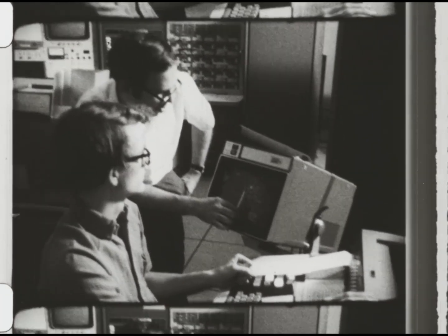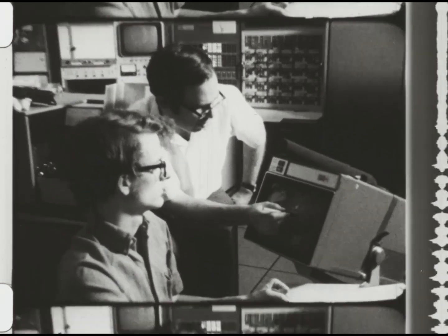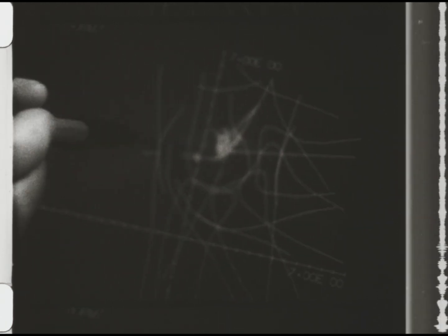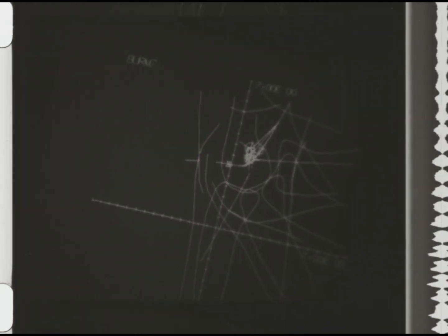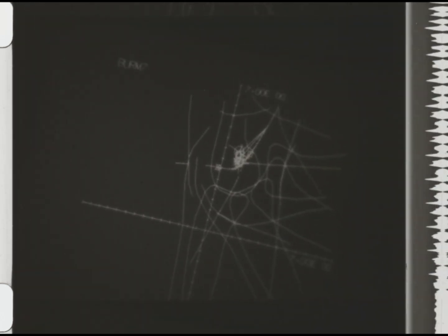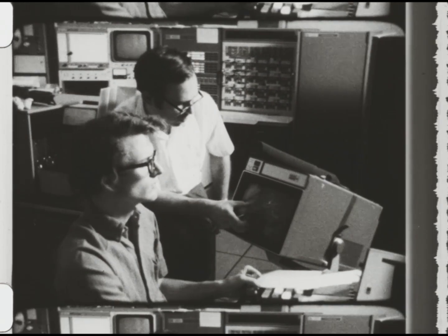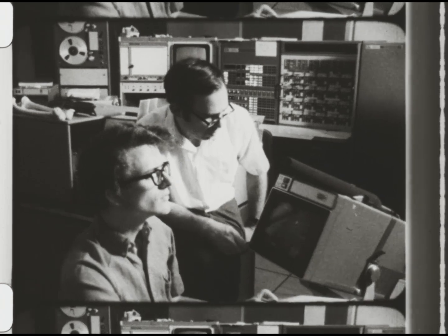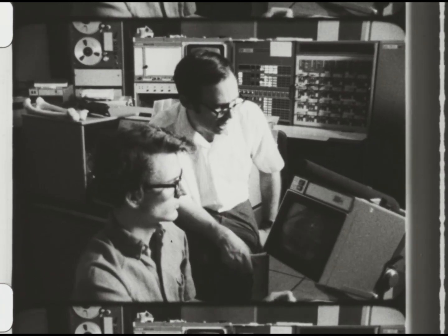See, the problem here is that if you were to pick a single pivot to move the body, say, from the first position to the second position, you'd need to pick a different pivot. The pivot would have moved as you went from the second position to the third position, and it would have moved again as you went from the third to the fourth position. So what this linkage does is it accomplishes this change in the position of that pivot, or that pole of rotation between the design positions.